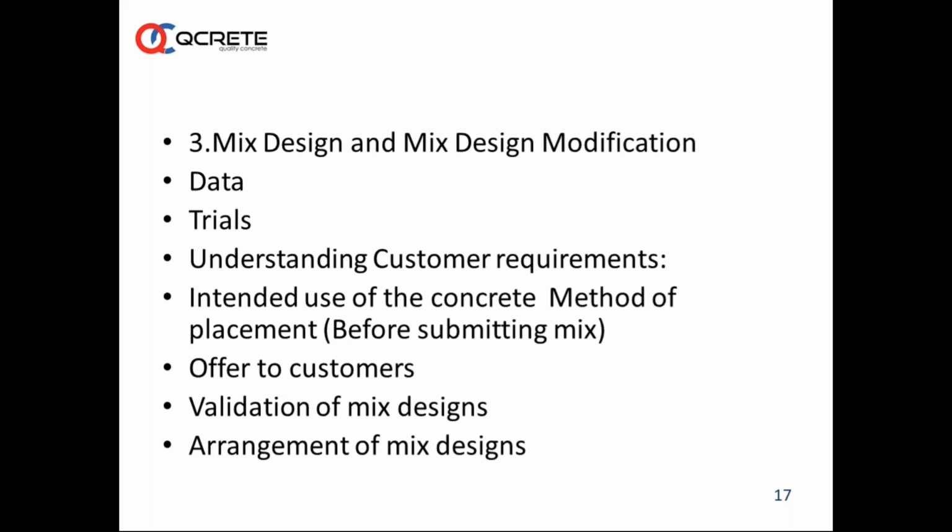So if a customer intends to use concrete for a floor or an industrial floor, he should discuss with the producer what he wants to use the concrete for, and probably also have meetings with the structural consultant to specify a minimum grade with a specific type of concrete. Otherwise, it will be difficult. And understanding these requirements is equally important for the producer. We need to understand completely before we submit the mix.